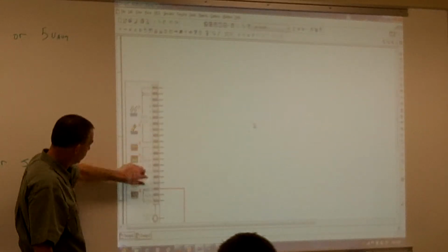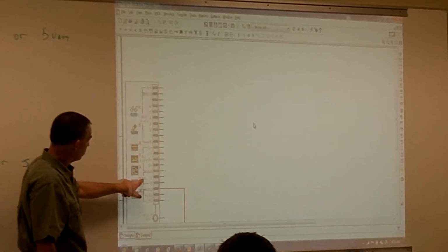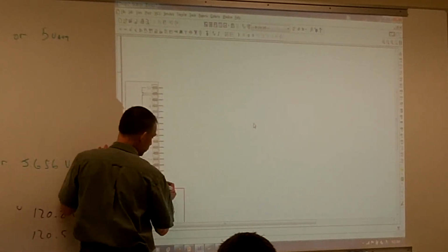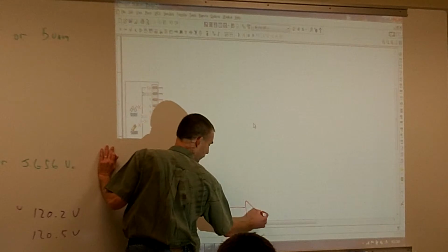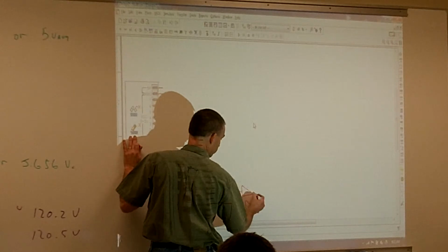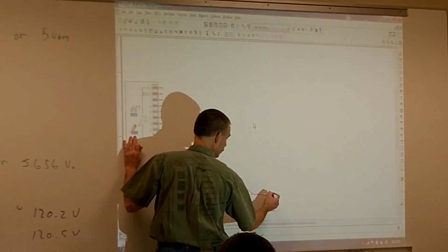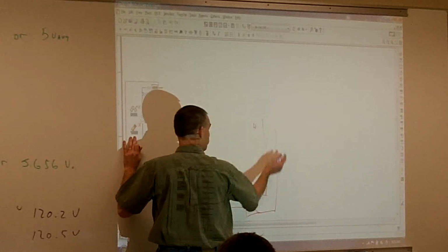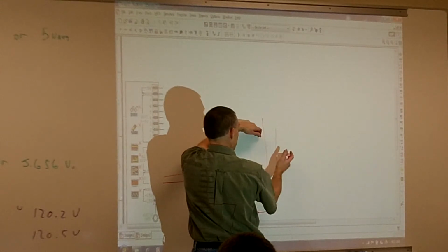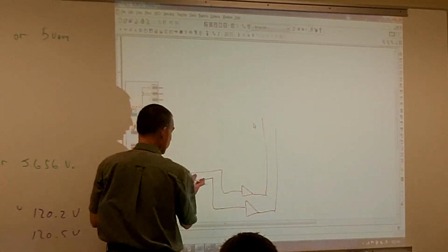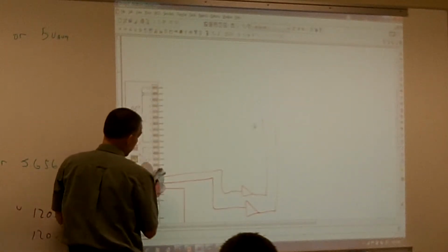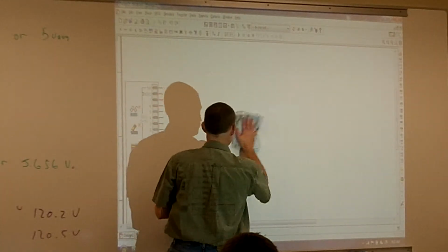So when I'm talking about AO0, those are my analog output. That's what the AO stands for. It's an analog output, and then it's channel 0. Now remember that these two channels, channel 0 and channel 1, are going down to our op amps. And then the outputs of those are going to our two buses, okay? So when I'm talking about AO channel 0 and channel 1, I want you to use those buses coming out of the op amp so that we have enough current going through there. Alright, but for our digital signal here, I'm just going to...